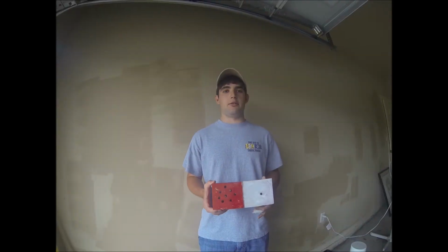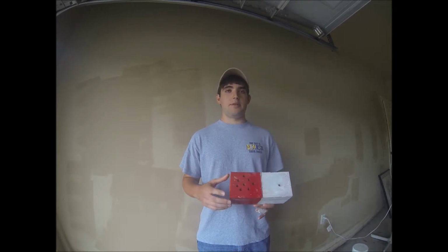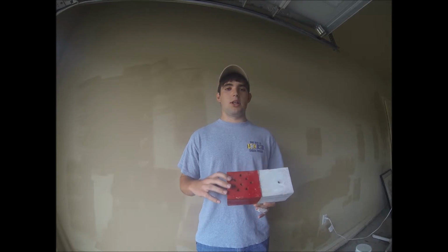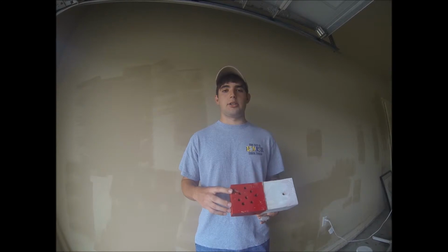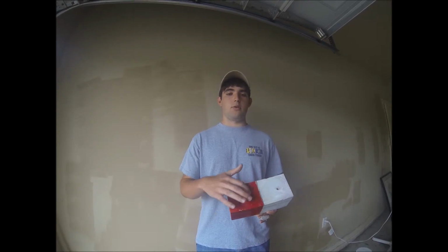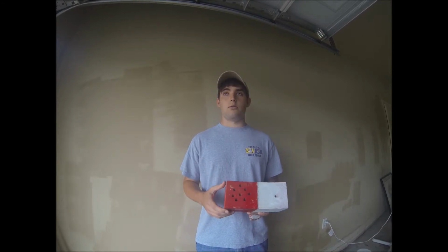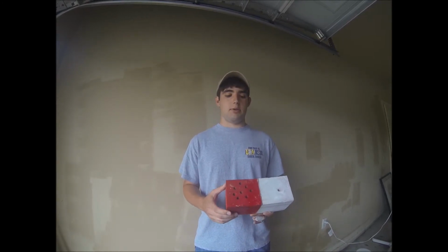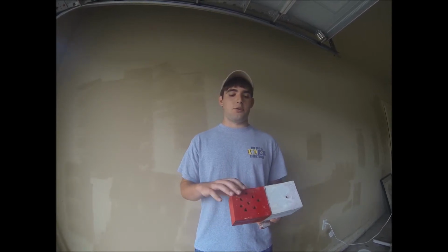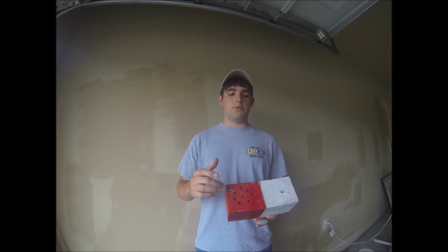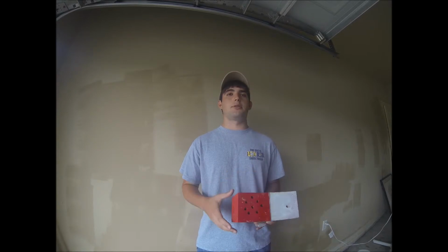We're going to show parallel flow. We're going to do this by showing how when water is poured over this block, it's going to be directed to flow to the colored side more than the white side. The reason for this is because the red side has more permeability due to the larger number of holes we have drilled in it, as compared to the white side, which only has one hole. We're going to show how the flow rates for the entire block are additive, by showing that when the water is flowing through, the total flow rate is going to equal the flow rate through the red portion of the block plus the flow rate of the white portion of the block.